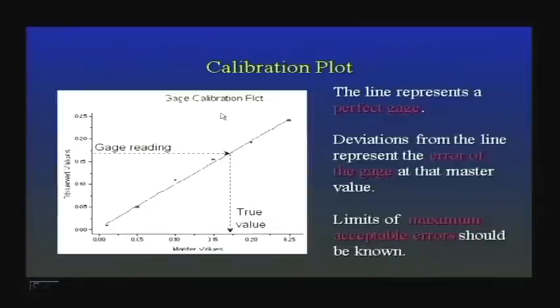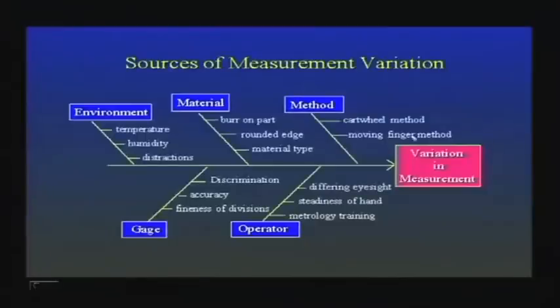Calibration is something that is invariably done. When you've got a good gauge, and a good gauge that is being used for research purposes, it must have a calibration chart with it. Otherwise, the data that you produce using this may not really end up being a good piece of data, and there may be questions about its validity. That's something we'd like to minimize to the extent possible.